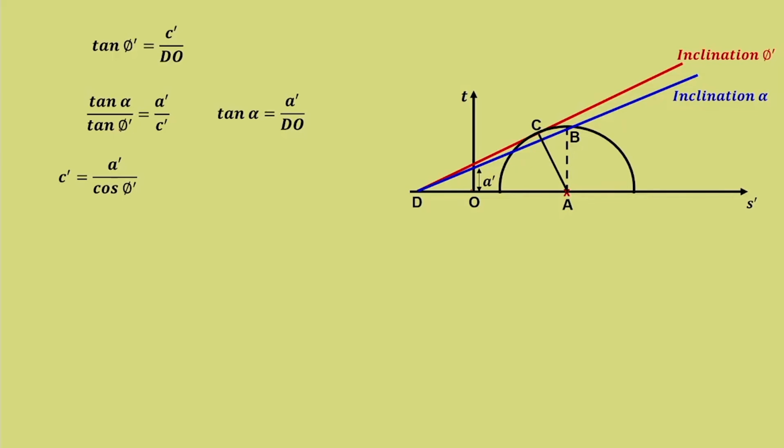Tan alpha, we have already proved, is equal to sin phi dash. Substituting that here in this expression, sin phi dash will cancel off and cos phi dash goes up. So, it will be A dash is equal to C dash cos phi dash. So, the slope of the failure line of the T S dash plot, tan alpha, is equal to sin phi dash.